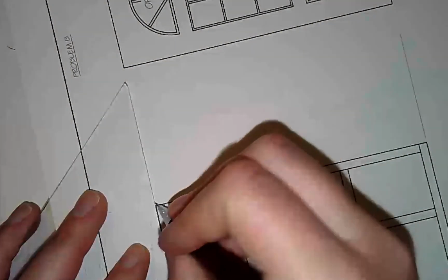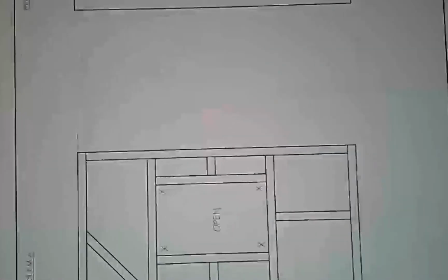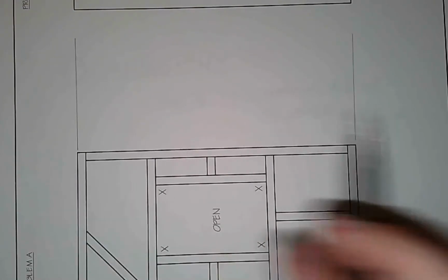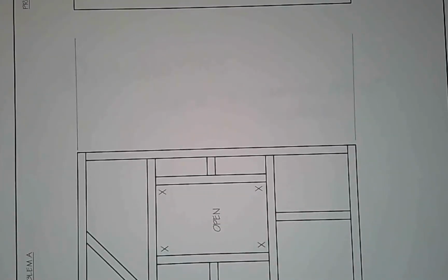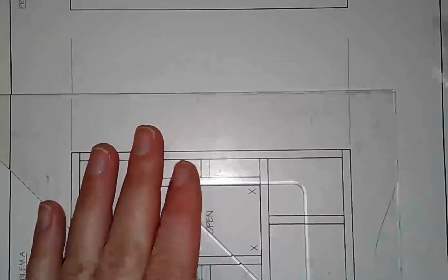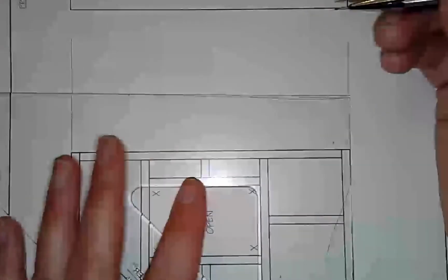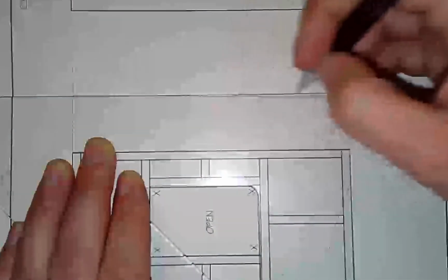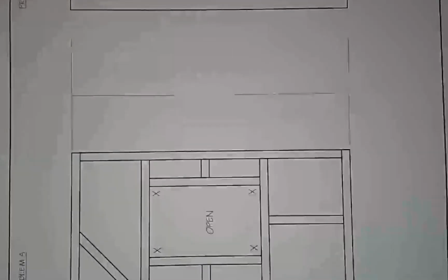And again, I'm starting a little bit away from the object and pulling it up. Okay, so those are my extension lines. Next are going to be any that are inside of that, right? So that's the most broad opening, and I can then create a dimension line that runs perpendicular to that extension line and connects these two. So I'll do something like this, and I'll leave a gap in the center for whatever that actual measurement would be, and then I'll use a filled, tightly filled arrow.